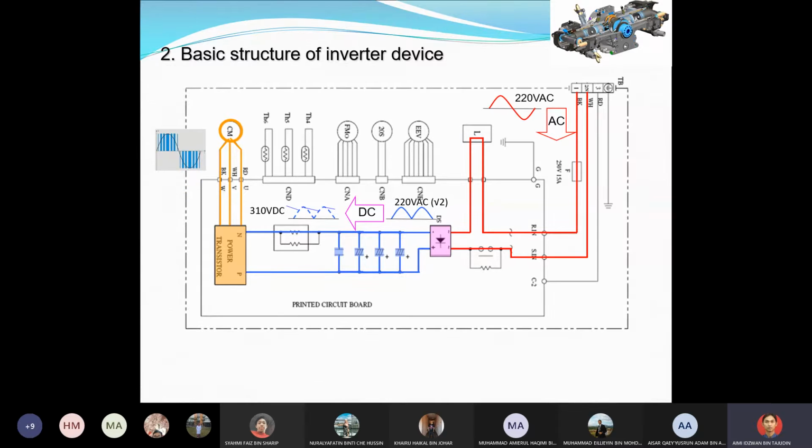The smaller and shorter the pulse, the smaller the value, and the wider it is, the bigger the value. So that is the magnitude. You can see the small ones are at the bottom, and then it gets thick in the middle, because this is the maximum point. Then it goes to zero, and then we have the negative PWM. This is the signal for the switching to convert to AC. The faster the frequency you have, basically the purer the sine wave you will obtain.